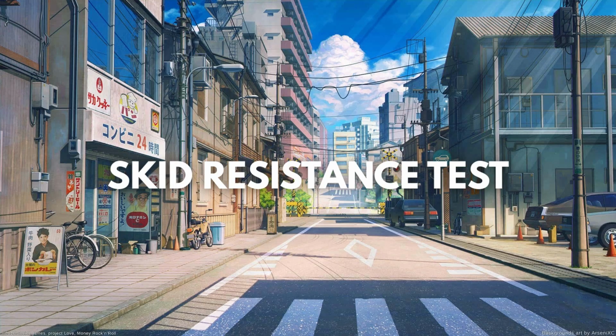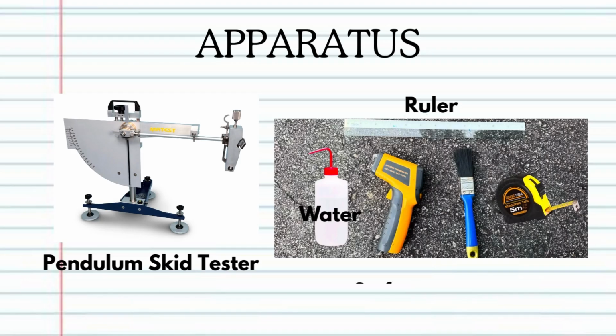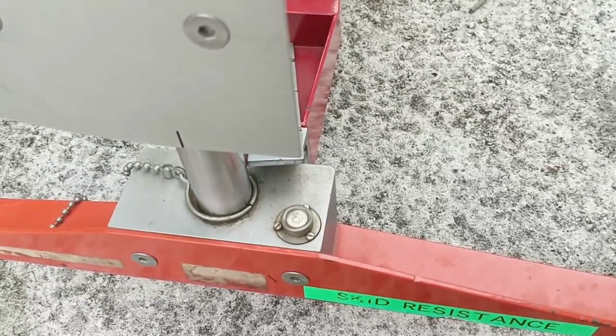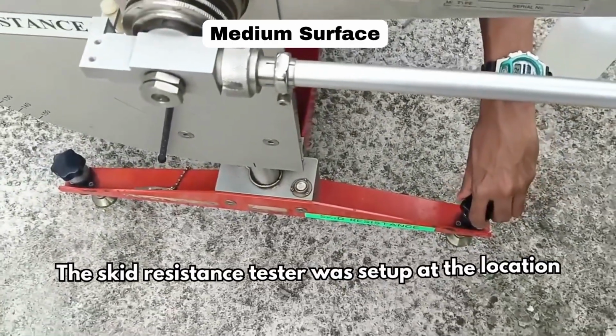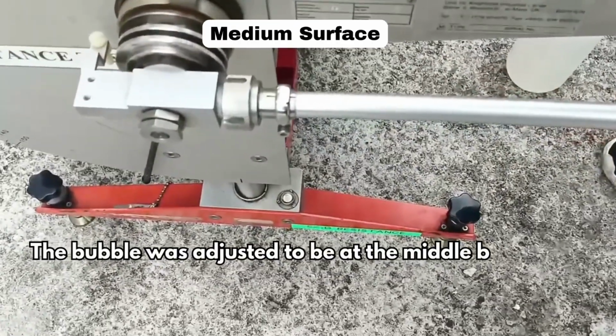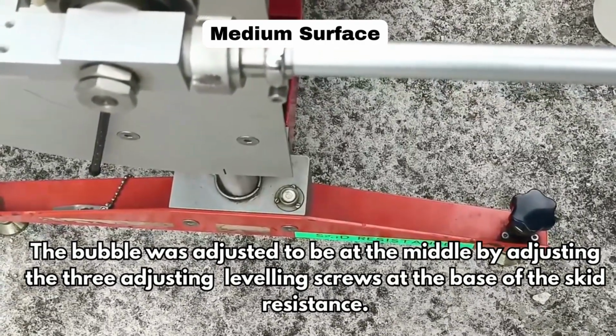Skid resistance test. The apparatus required for this test is pendulum skid tester, water, ruler, surface thermometer, brush, and measuring tape. First, we will conduct the test for medium surface. The skid resistance tester was set up at the location. Then, the bubble was adjusted to be at the middle by adjusting the 3 leveling screws at the base of the skid resistance tester.